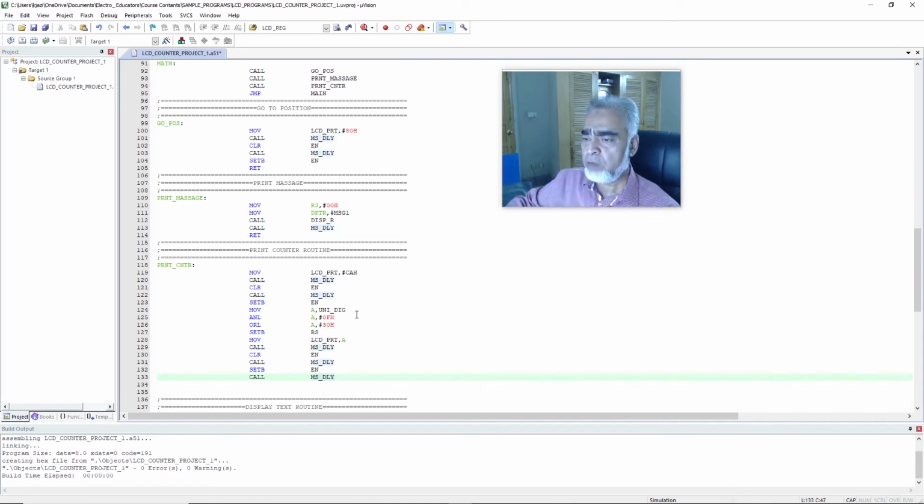Here we have written the value of the unit digit to the address CA, and now we will write the value of the 10 digit to the C9 address. So we'll repeat this procedure 2 more times to print the 10 digit and 100 digit on the LCD display.